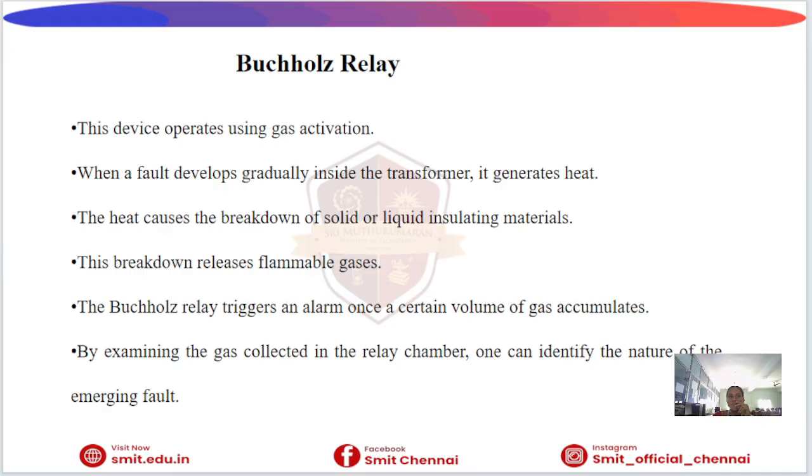Then, Buchholz relay. It is a gas-operated relay used in oil transformers, and it detects faults by sensing gas formation. Gas is produced due to insulation failure. It gives an alarm or a trip signal. The trip signal makes the circuit breakers disconnect the circuits.